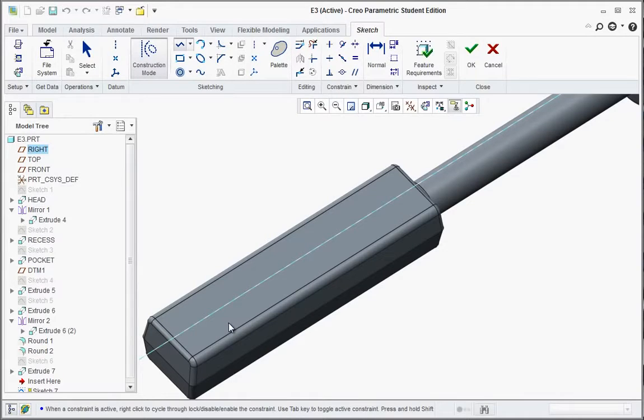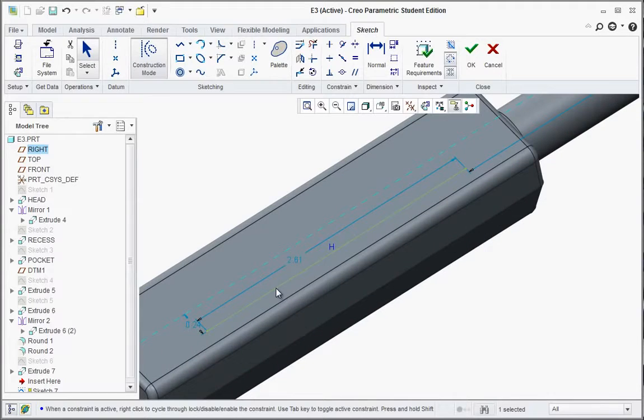Like you're drawing the baseline for the text. So I want it to start right about there to right about here. Okay. Now with that selected, turn off construction mode. Click on it again to turn it off. Go to the A, that's right there, that's for text, and glide up to this point that you drew. Click and drag up the vertical length or height of the letters that you want for the text. So I'm just going to eyeball it right here.